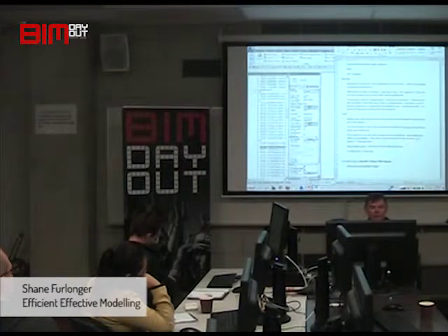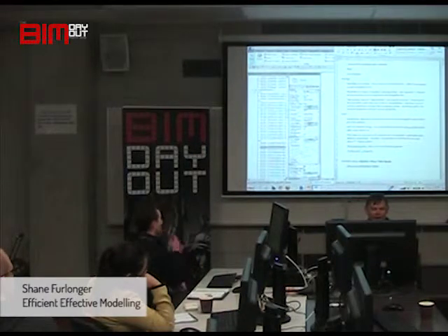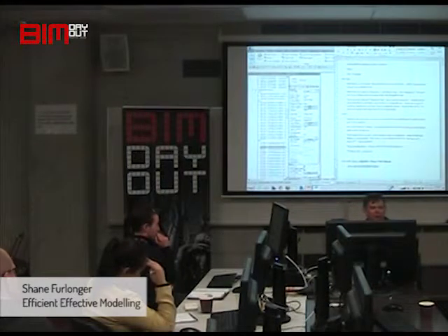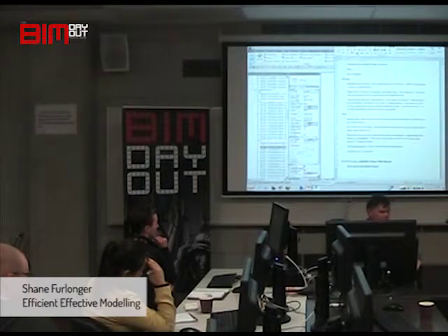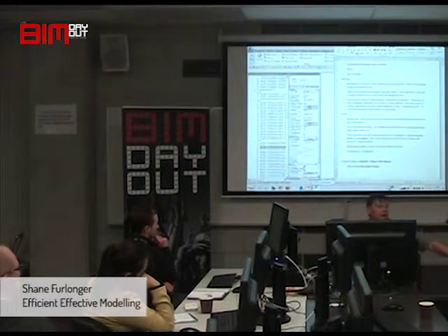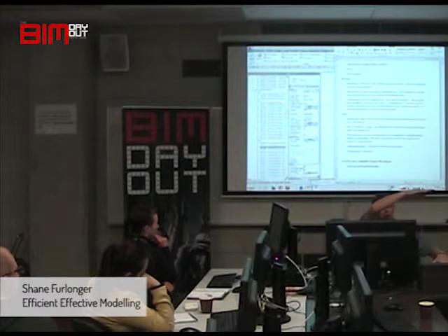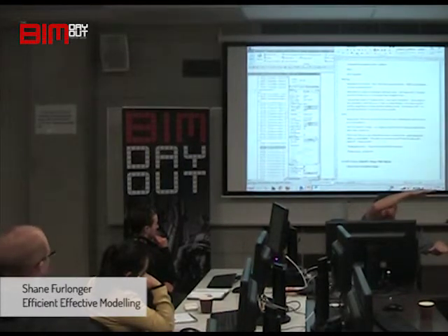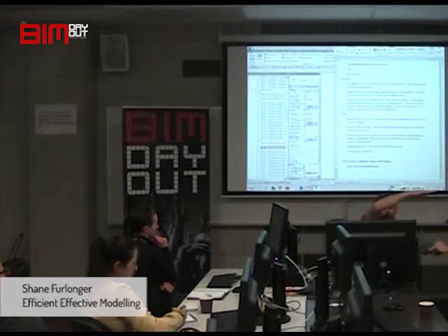It can create problems. I only use unconnected when I know I want the wall to be an exact height all the time. If I had, for instance, a balcony set level with the structural floor, offset off that level by 1,200 or 1,000, and that has to be what it is. So I could say, okay, I know that's got to be 1,000 off there all the time. Yep. So I can use unconnected.